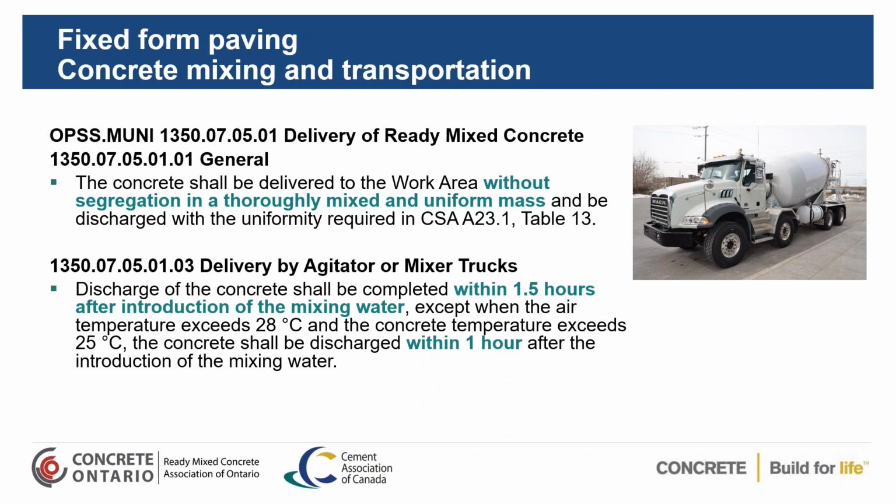Now, what's also important in the 1350 is the delivery of the material. There's a time limit to mix and discharge that material into place, and that's 1.5 hours after introduction of the mixing water, except when you have higher temperatures. When you have a higher temperature, the concrete will be discharged within 1 hour. And again, you have to look at this from a practical point of view. What are the environmental conditions that you're dealing with? And do you even have an hour if you are having a very fast set because of very hot weather? You'll have to go into hot weather concreting techniques.